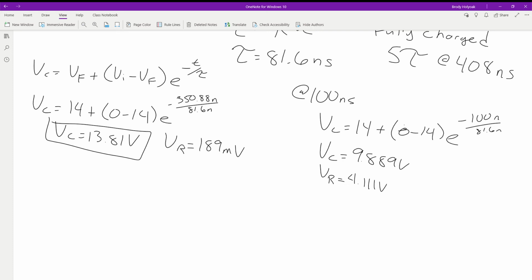The capacitor would still charge to that same value. It would do it quicker. And so what you're going to see is, because our voltage supplies have some internal resistance, we try to make it as small as possible, as close to zero as we can get, but there is some resistance. So the rest of the voltage that the cap doesn't see is being dropped across our supply. That's why it'll change the numbers, and then it'll ramp up, and then it caps out at whatever the set point is. So internally in the power supply, there's some voltage somewhere that's being dropped.